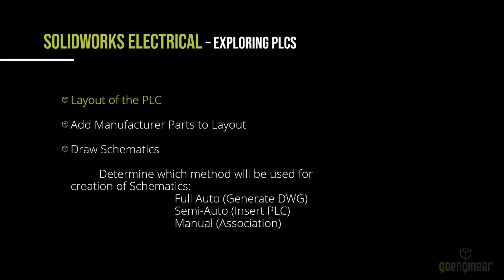So that is strictly how you lay out a PLC. Very straightforward. Now, some people ask, well, why did you do it this way? I normally just do symbols on a page, and then I start placing those symbols, those manufacturers for that specific symbol. There are reasons that I am showing you to do it this way. This is more of a best practice, or I don't want to call it a best practice, but let's call it a sound practice. By doing it this way and laying out the PLC first, even before you add manufacturers,